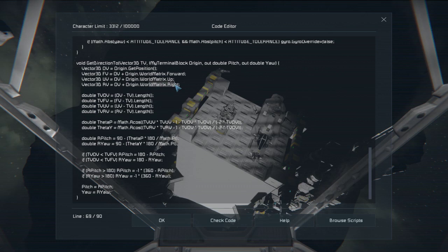And those are what we need to figure out to get the pitch and the yaw to turn it so that those angles become 90 degrees and we're pointed straight at it. We're trying to zero out that turn, basically. That's the goal: to make it so that the pitch and yaw that we need is 0. So 90 degrees from right to the target, 90 degrees from up to the target. Up being pitch, right being yaw.